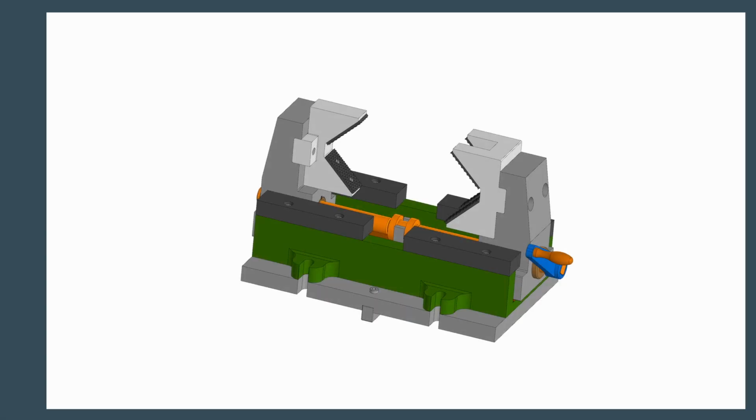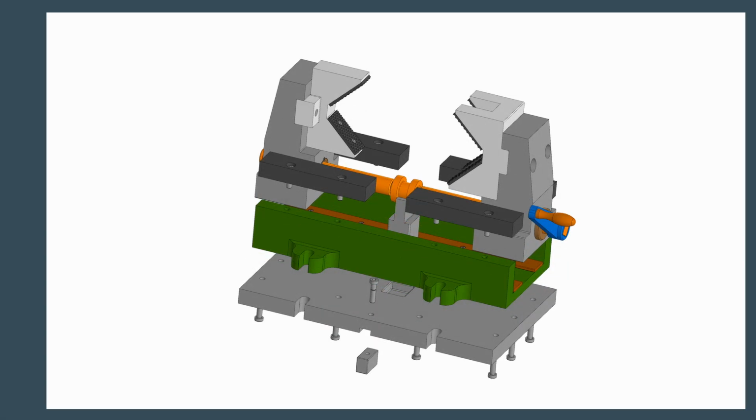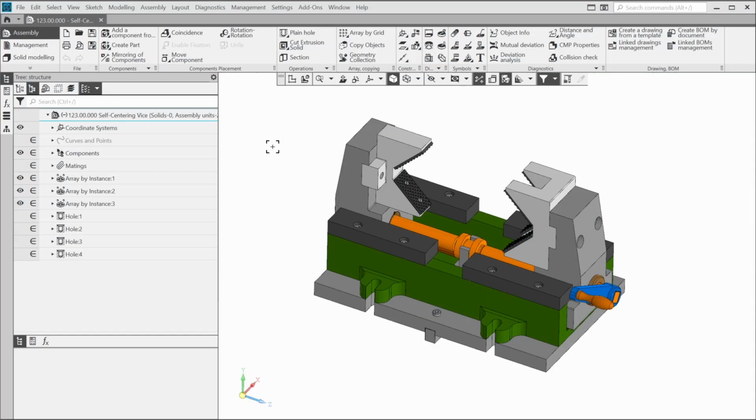In this lesson, we'll learn how to create and adjust exploded views. An exploded view shows an assembly's components spread apart, but positioned to show how they fit together when assembled. To create the explosion view, start the Explode Components command in the Quick Access bar.